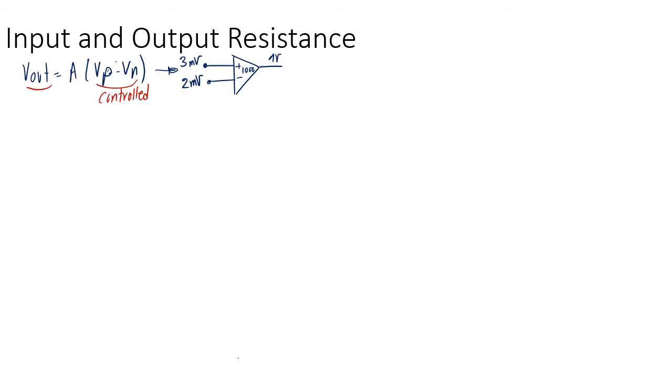And it doesn't matter if I connect a resistor here to ground, or a bunch of resistors with a voltage source, or another current source here. It doesn't matter what I connect to this node. It's always going to be 1 volt because it's the output of the op amp which is controlled by the two inputs. That is the definition of a voltage source.